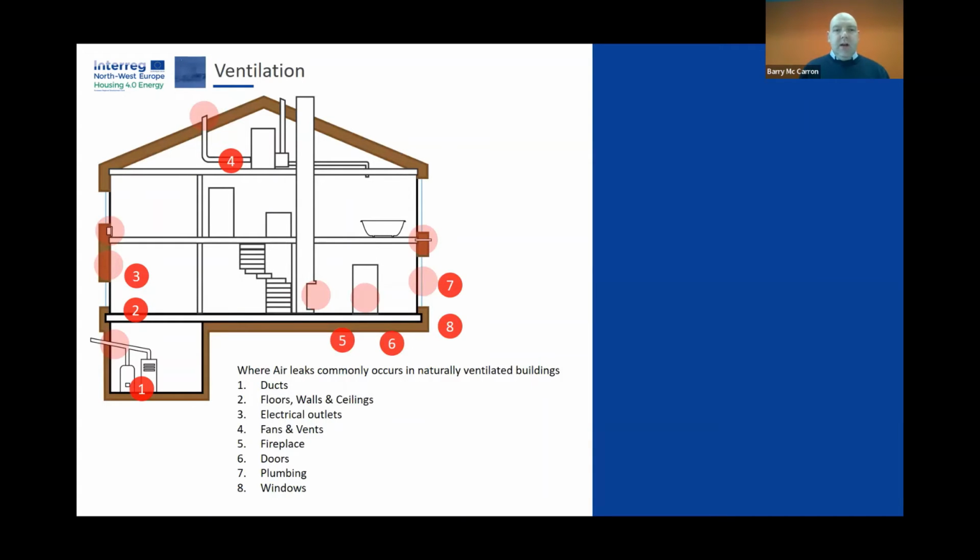So here's an illustration of the typical points in the building where we have infiltration happening, or indeed exfiltration, because there are penetrations in the building. When looking at air tightness, once you have a bit of experience with it, it's quite simple to combat really. But what I would say when presenting about this is that if you don't have mechanical ventilation, which we say in the industry, controlled ventilation, then your other strategy, without air tightness and mechanical ventilation, is honestly, probably the best way to describe it, random ventilation.